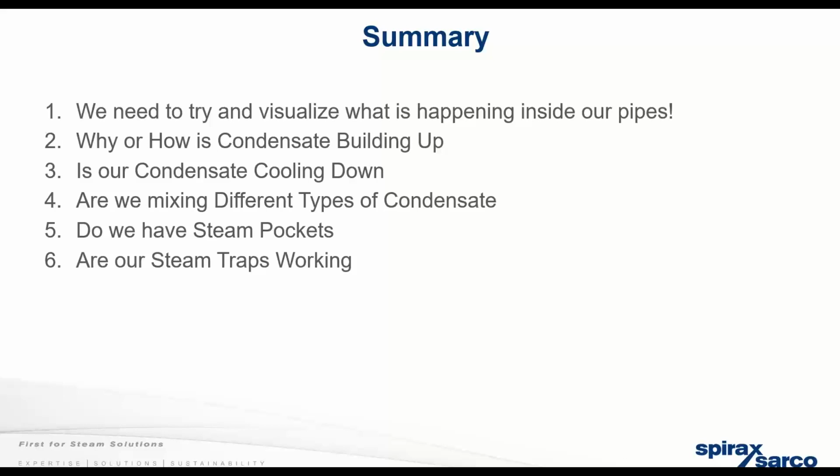The big thing discussed in the initial slides was draining. We're always draining. Everything's draining. We need to drain at close to temperature of our steam temperature. So our condensate temperature has to be the same as our steam temperature, or very, very close, and then we prevent water hammer. Are we mixing different types of condensate? We can mix different types of condensate with engineering controls. We can. But if we're having water hammer, we're not doing it properly. So we have to consider that. Are we mixing high temperature condensate, pump condensate, without engineering controls?